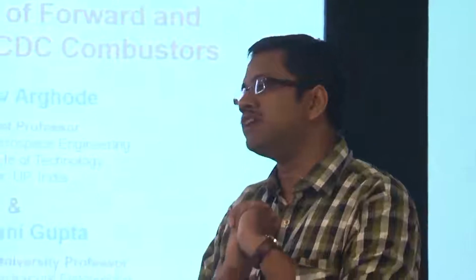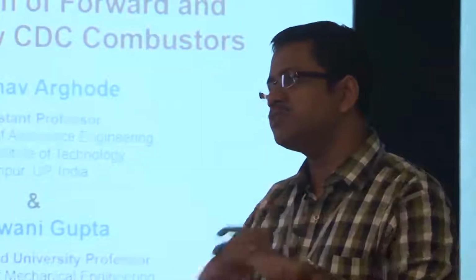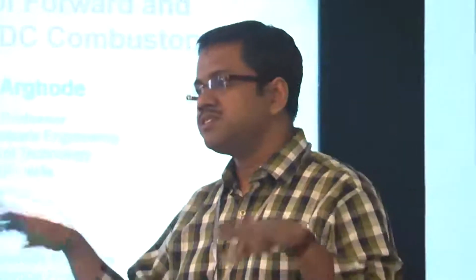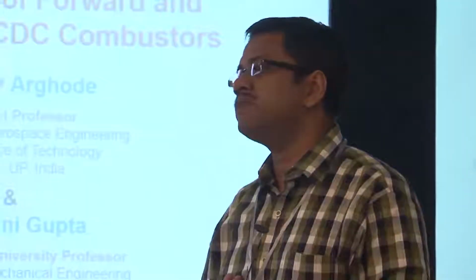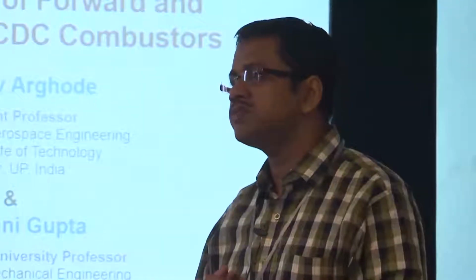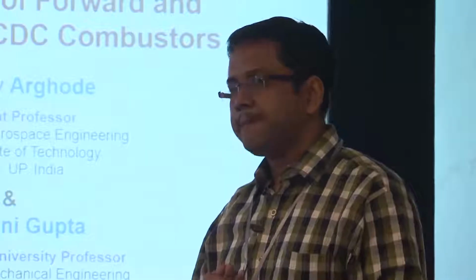Co-flow temperature? This is all isothermal, room temperature. In the other one, it is basically room temperature too. So you ignite it and then it is that kind of flame. So it's partially premixed, I would say. It is still not fully premixed, but because you have such strong swirl influence, it's hard to believe it is a complete diffusion flame also. So there is a partial premixing. Probably LIF kind of studies will reveal some of that. Yes, there would be a lot of physics coming from that. So we will look into all these things in a little more detail.